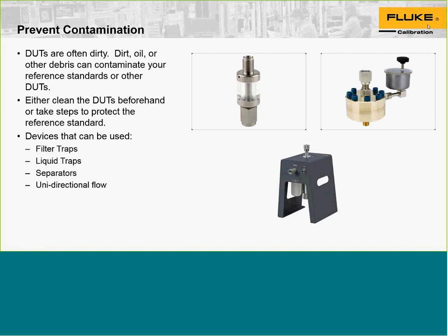Then you have separators. For example, here this is a liquid-to-liquid separator. So there's a diaphragm in the middle, so the two media never actually come in contact with each other. Instead, pressure from the standard on the bottom pushes up on the diaphragm, changing the pressure in the top half of the system where the device under test is connected, resulting in a compression between the two